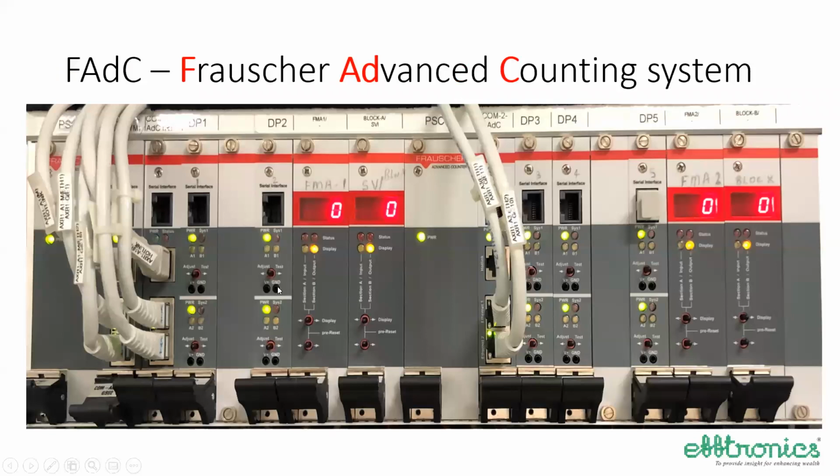Equipment looks like this. You can recognize the cards. This is the AEB card. You can see system 1, sys1, sys2. This is 2 out of 2 principle. And this is another card for the DP2. And these things you can see: IO board, IO extension board. And the card which is connected with a number of cables, this is the communication card. So here in this board, we are able to see 1, 2, 3, 4 IO cards, IO extension cards, which provide the outputs and take the input for reset. And then 1, 2, 3, 4 sets of AEB cards. You can see 1, 2, 3, 4, and there are 2 COM cards, or 3 COM cards. The third one is here, not visible inside.